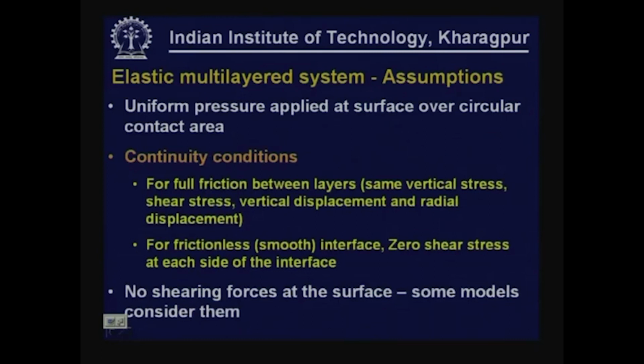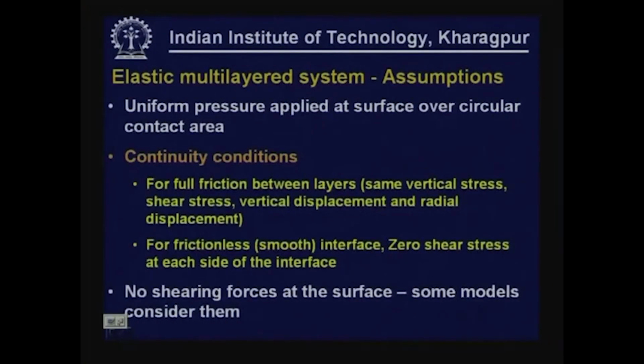We can also analyze the pavements for a frictionless interface, assuming that the interface between different layers is smooth, that leads to zero shear stress at each side of the interface. We normally do not consider shearing forces at the surface, although some models are available which are capable of analyzing pavements for surface shear forces.